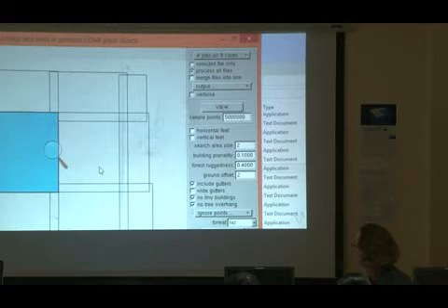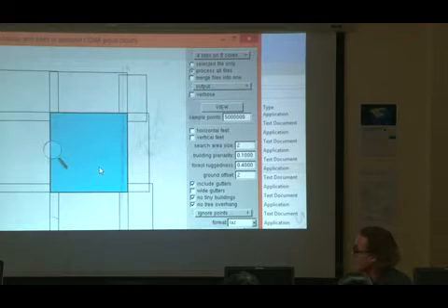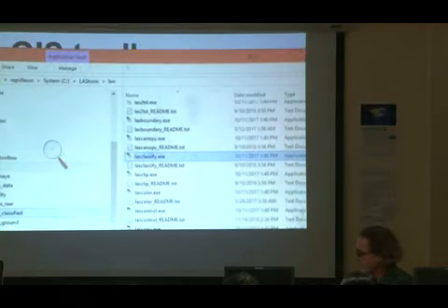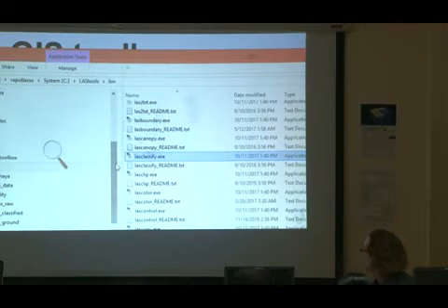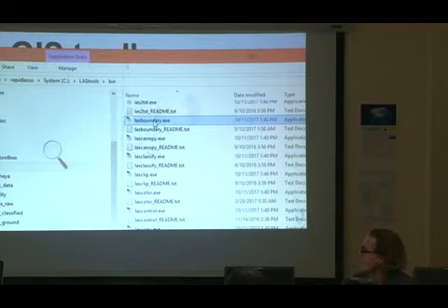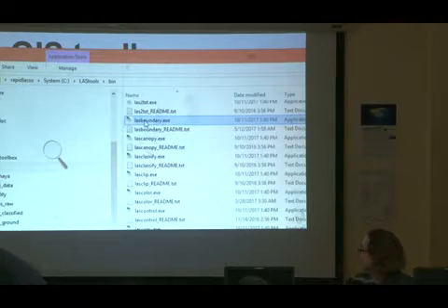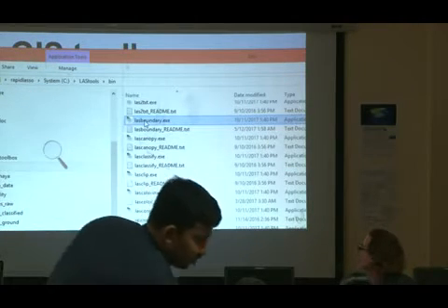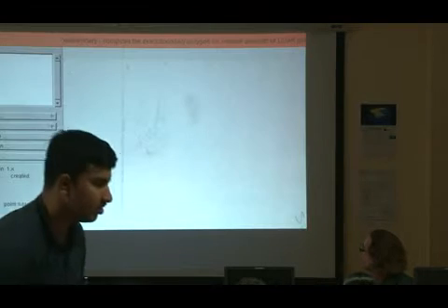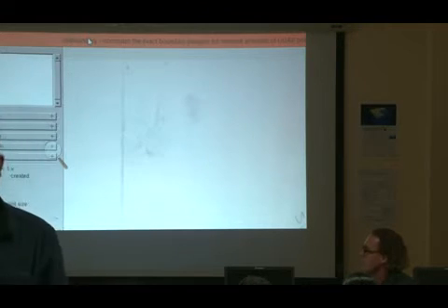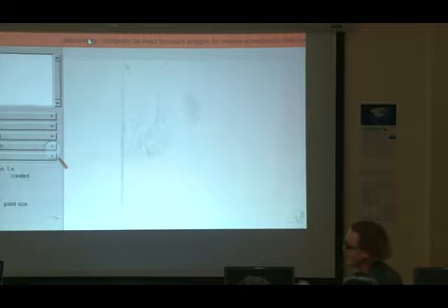Okay, so that's done too. And that's all the LiDAR processing I want to do for today, I think. Now I want to create derivatives. One of the derivatives I can create is I can try to extract all of the buildings using lasboundary, at least approximately. So I'm running a tool called lasboundary. I'm speeding up a little bit so we see some results.